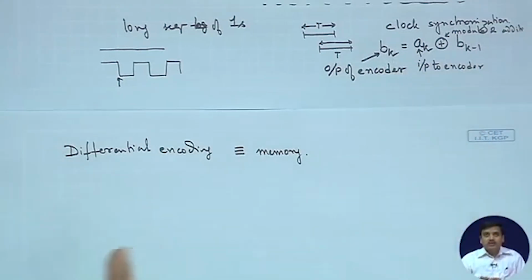So, when we discussed memoryless and with memory modulation, we had stated that memoryless modulations are those where the current output does not depend on the memory, that means whatever signals have been transmitted in the past symbol intervals. Whereas, the ones with memory are those which use reference to the past, that means information about signals that have been transmitted in the past.